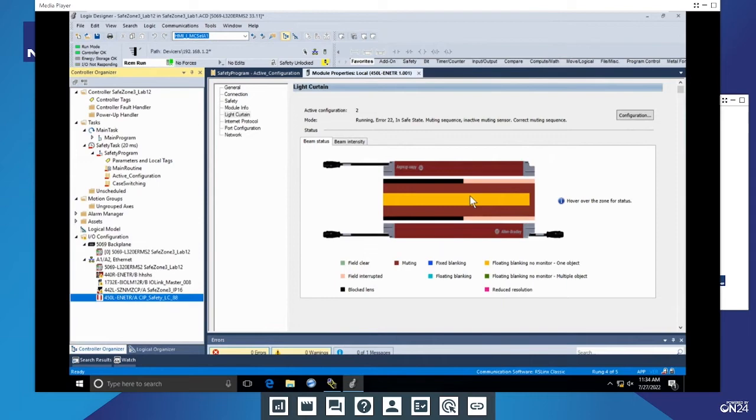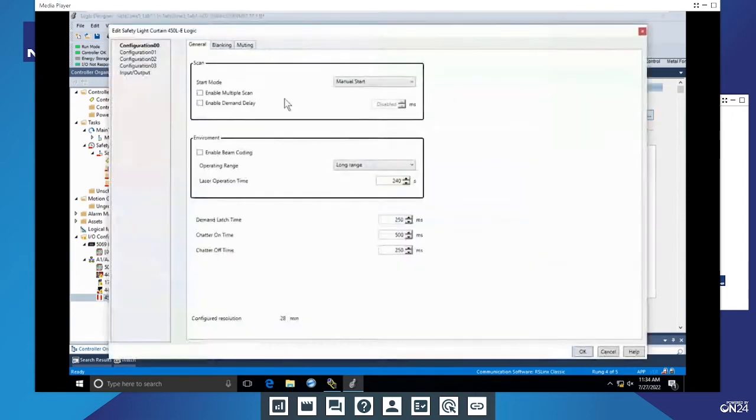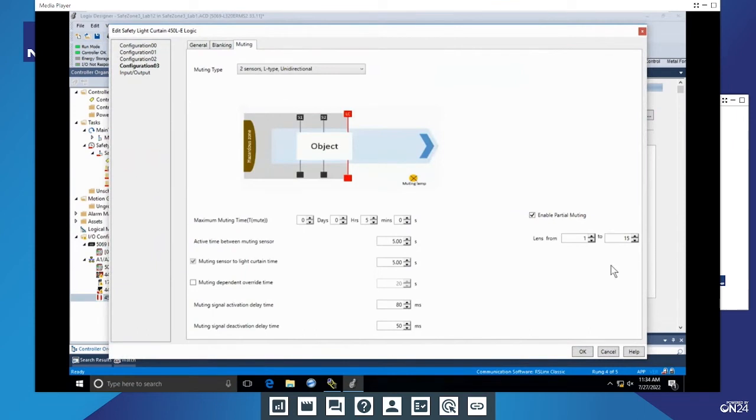So now what we've seen is we've got two sizes of product going through, but we want muting. But we also want to ensure that the muting is done for that specific product. Then what do we do? We go to our configurations tab and we enable our partial muting here. This way, we know that only one type of product is going through. So what I'm saying here is 4 production lines all converging into one, which then allows us to have different product profiles at different times. This is also a check to ensure the right product is going through.